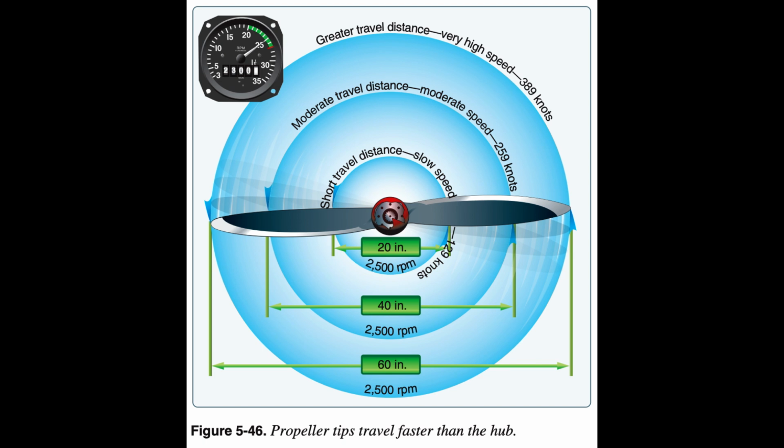After liftoff, as the speed of the aircraft increases, the constant speed propeller automatically changes to a higher angle, or pitch. Again, a higher blade angle keeps the AOA small and efficient with respect to the relative wind. The higher blade angle increases the mass of air handled per revolution. This decreases the engine RPM, reducing fuel consumption and engine wear, and keeps thrust at a maximum.